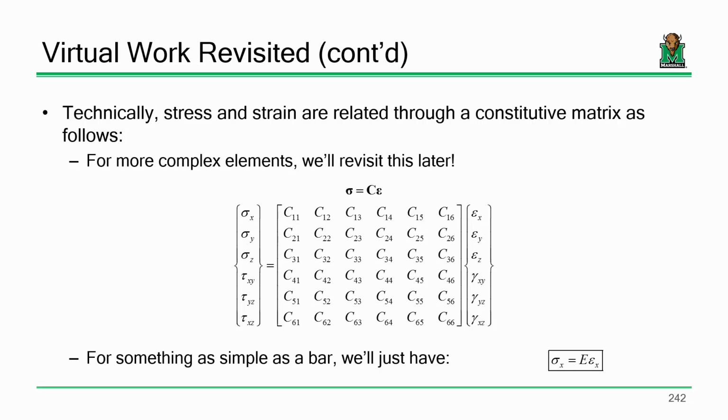How about, for those of you material folks, does anybody remember the word orthotropic? Does anybody remember that word? Orthotropic materials have different properties in one direction than they do in another. Wood is strongest along the grain. Across the grain, it's weak. That's why when wood splits, the grains split apart. That's because that's where it's weak, right? What about something like concrete? You all have got to know what's the issue with concrete.